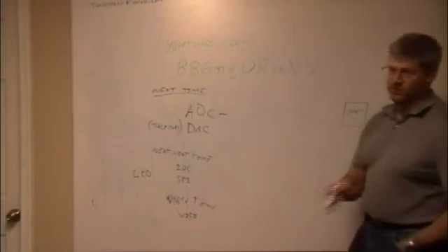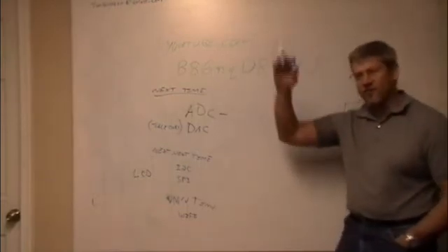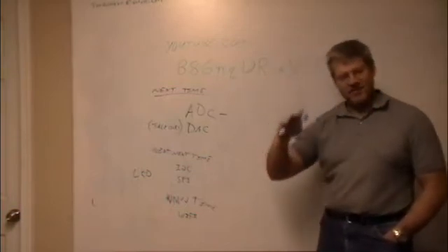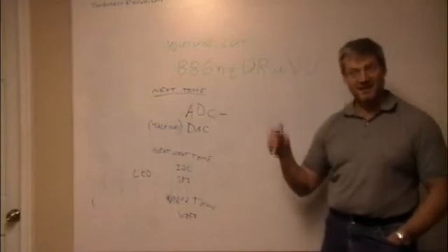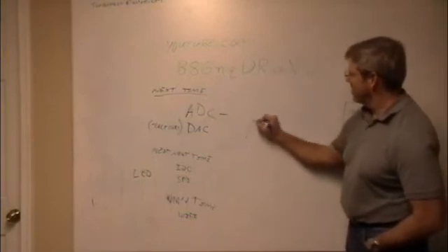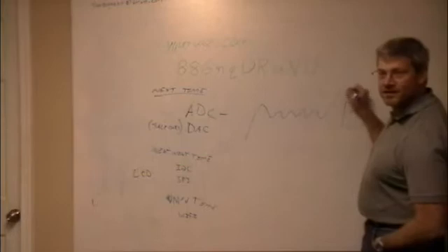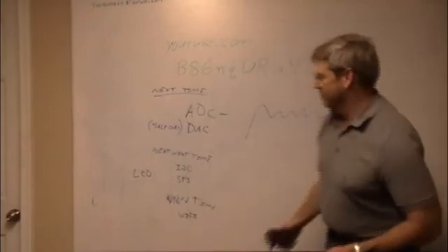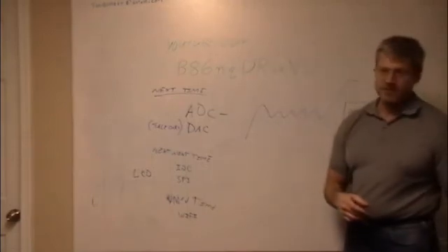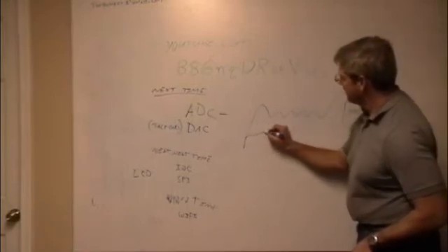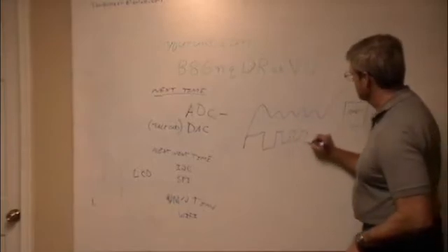So what happens is you're basically doing a PWM. I turn it on all the way, and when it gets where I want it, I turn it off, and it'll overshoot some, and then it'll come back down. When it starts getting too cold, you can hear them click, tink. It turns that switch back on, and when it gets above, it tink, turns it off. This is the ripple that you just can't control because it's a bang bang system. So I end up seeing a square wave that looks like this, but it averages.